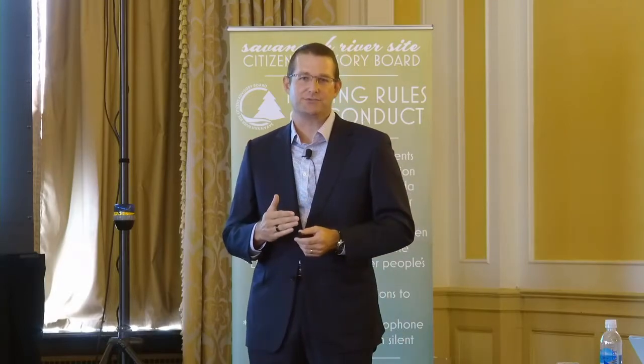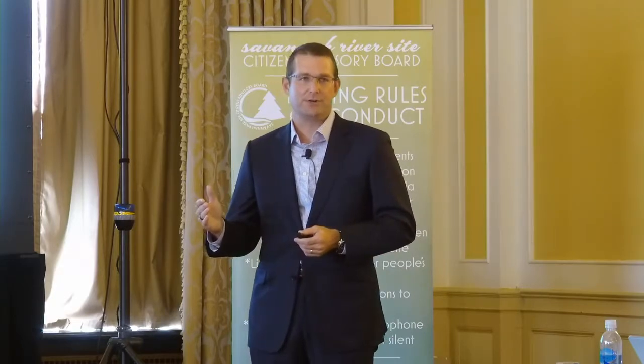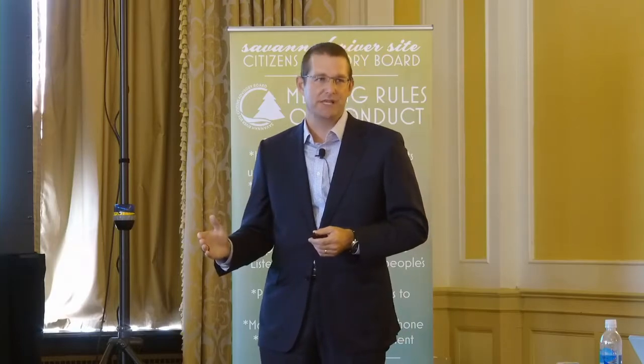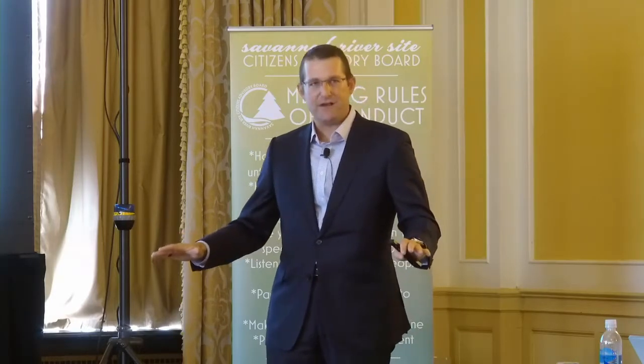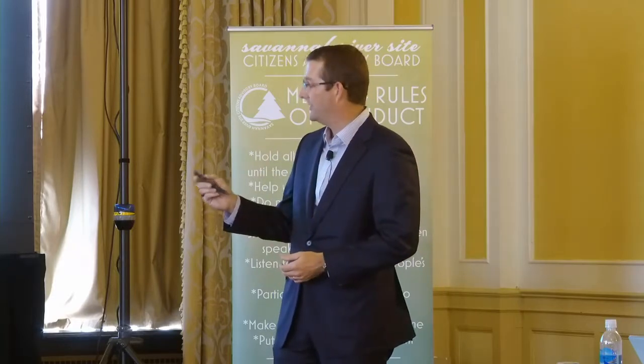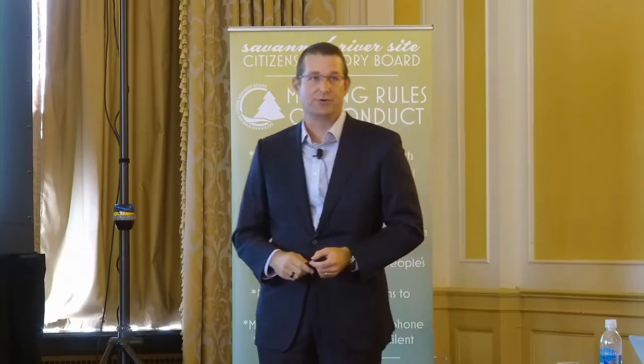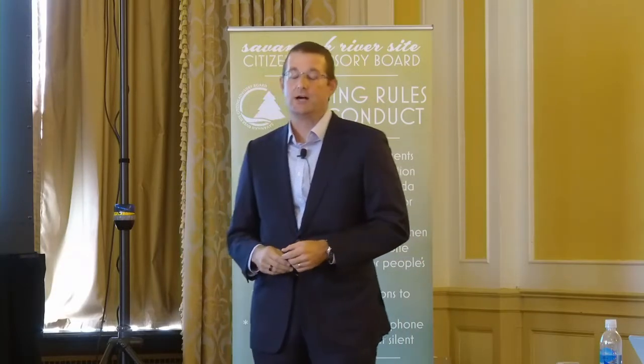However, as I said before, we operate at a very high instantaneous rate. If we are operating at 30 to 35 tons per hour of dry materials, we are consuming salt solution at a rate of about 80 to 90 gallons a minute. So if I had two 55-gallon drums up here, we are consuming that quantity of material every 90 seconds. So at that instantaneous processing rate, we could operate on a days-only operating schedule. So originally, Saltstone was intended to run days only, Monday through Thursday, unlike facilities like DWPF, which operate 24/7.